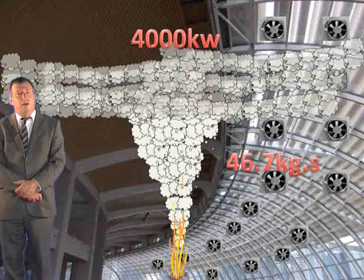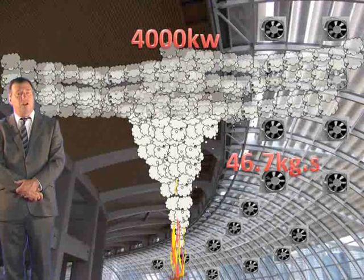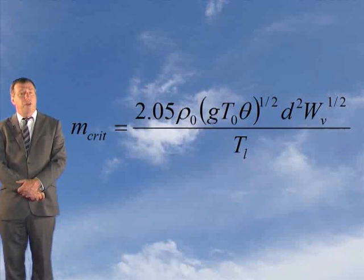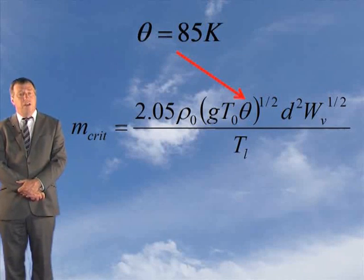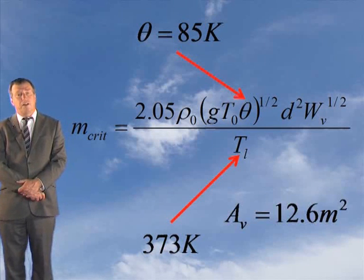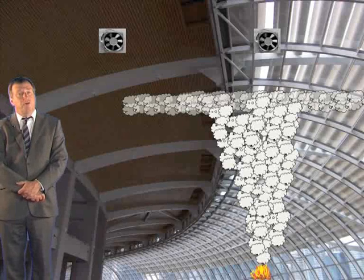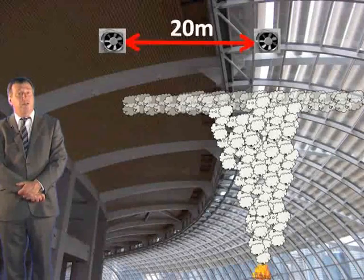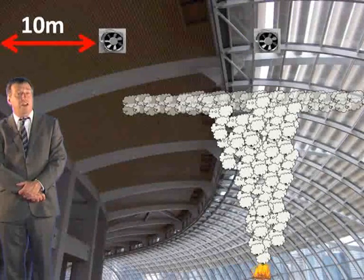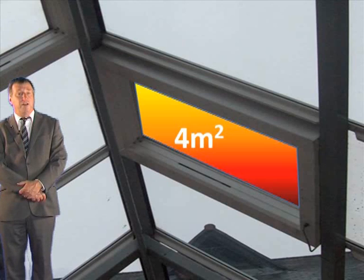Using our last example, where the mass flow rate was calculated at 46.7 kilograms per second, we calculated theta as being 85 Kelvin and TL as being 373 Kelvin. And the required aerodynamic free area of ventilation per reservoir was 12.6 square meters. Let's suppose that the designer has checked that the 20 meter and 10 meter rule for stagnation has been adhered to, and that ventilators with a geometric area of 4 square meters have been selected.